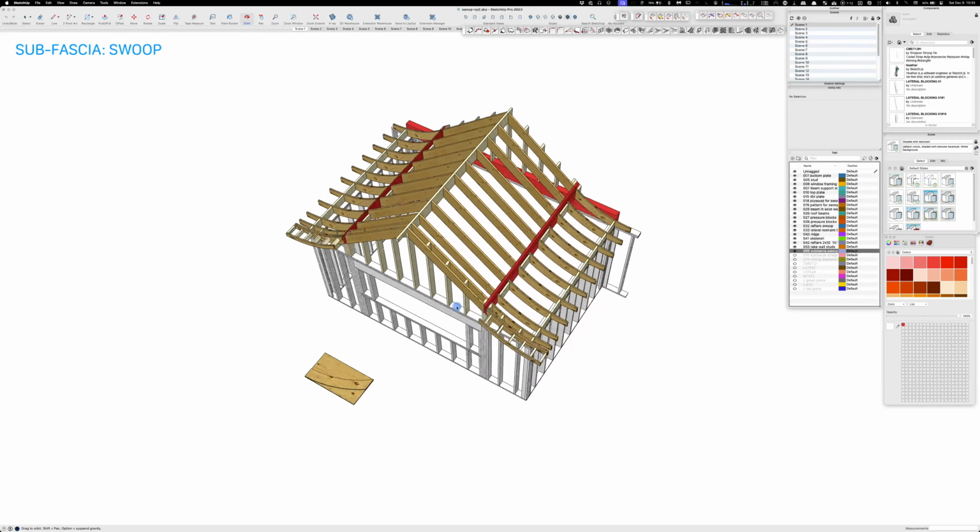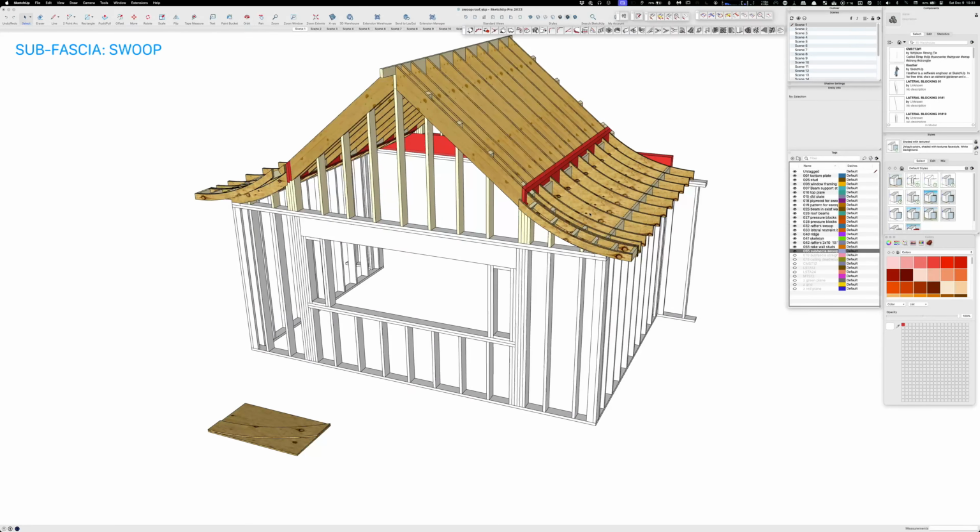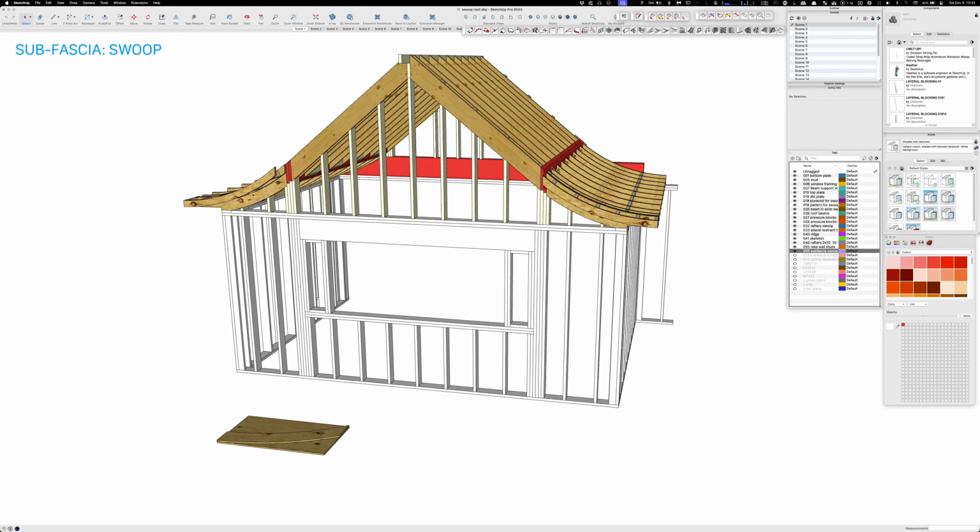Okay, so there's the swoop. So I don't know. I just looked at it, and there's a couple things I have a problem with. This swoop comes down to almost being like a 0 and 12 at the end. And I don't know where this is, if it's in Massachusetts and they get lots of snow. The snow comes down, and it's going to pile up right here on the edges, on the tails, because it's not even a slope to let the water run off.